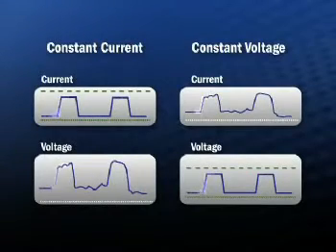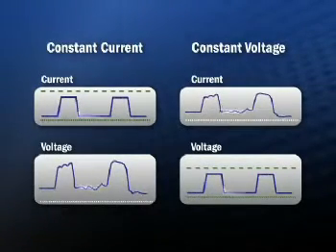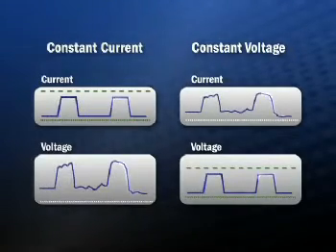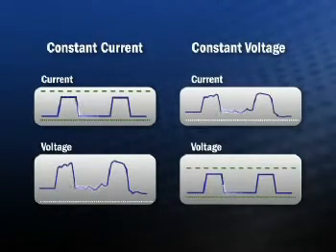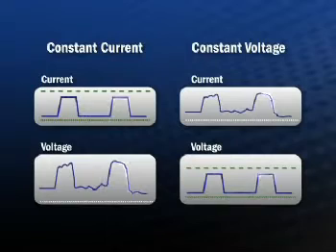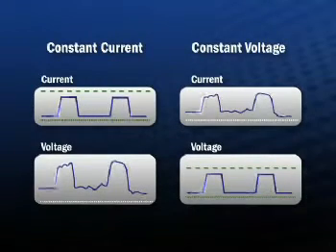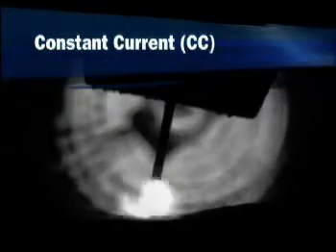Welding machines are usually classified as constant current or constant voltage. A constant current or CC machine will vary its output voltage to maintain a steady current, while a constant voltage or CV machine will fluctuate its output current to maintain a set voltage. GMAW pulse welding allows the use of CC in the MIG process by rapidly alternating between a target peak current and a target background current. This rapid transition detaches a droplet of molten metal and transfers it across the arc. As it is a modified spray transfer, it is possible to prevent short circuits and eliminate spatter.